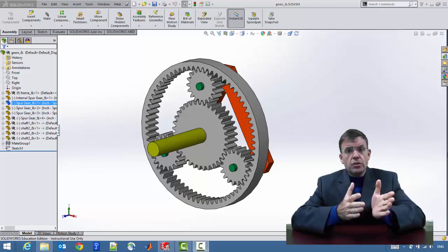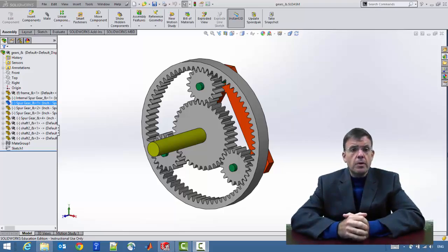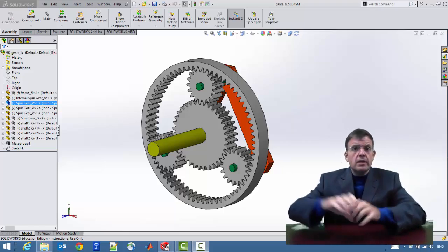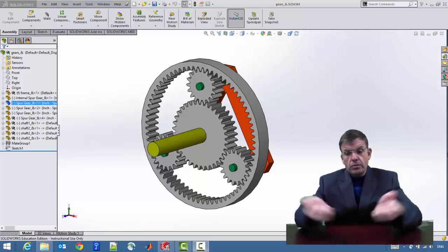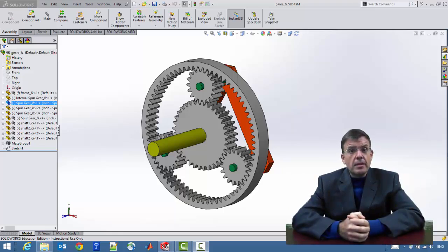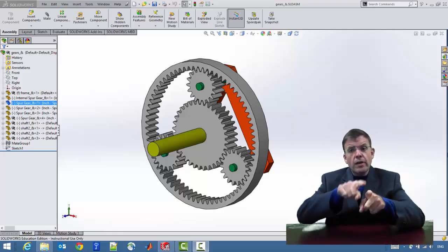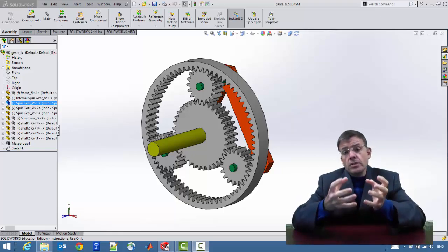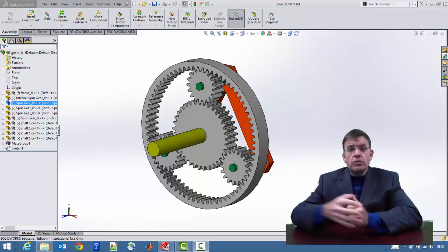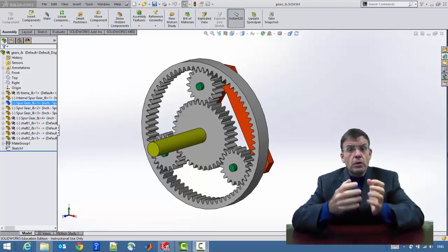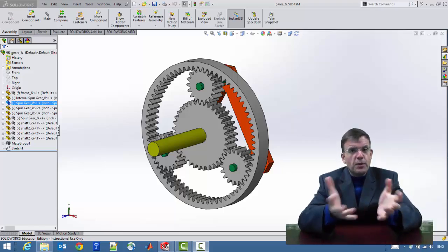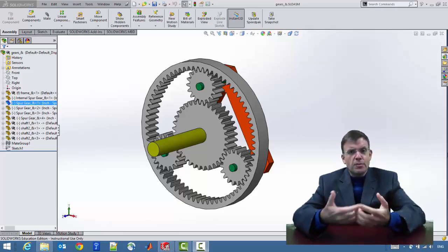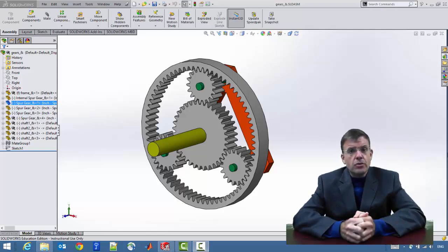So in SolidWorks, as you create constraints between components, say if you have a collection of bars that are linked in a serial nature, and then you finish them up at the end, the mere act of having declared, for example, concentric constraints at each one of the joints, at each one of the hinges, if you want to think of it that way, will already give you the kinematics of that device, let's say for free. What I mean by for free is that there's no additional programming, there's no additional action on your part.